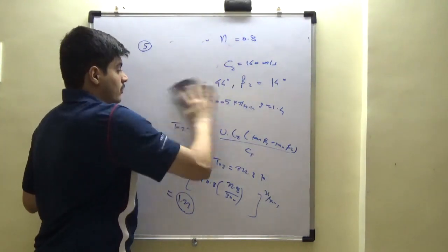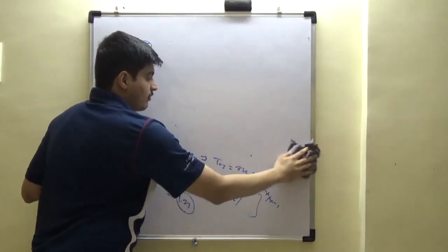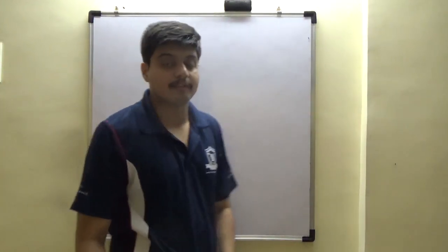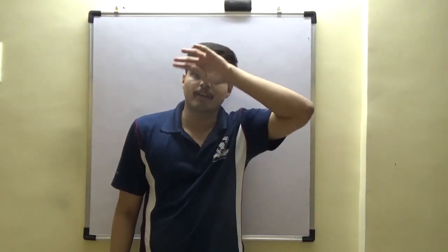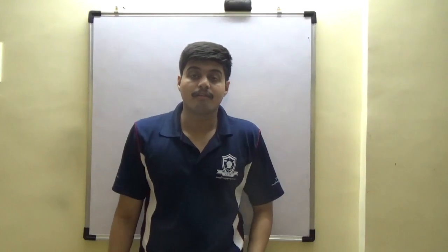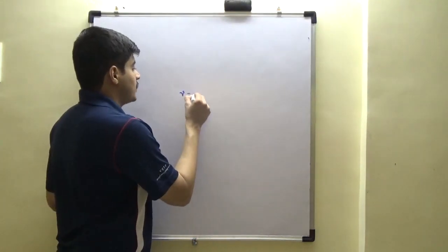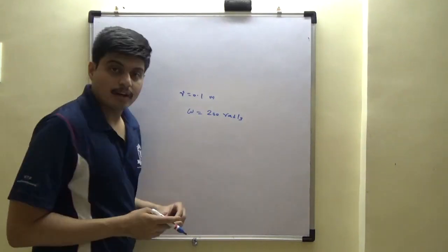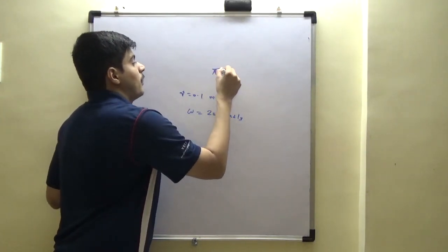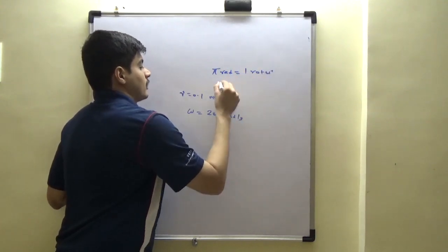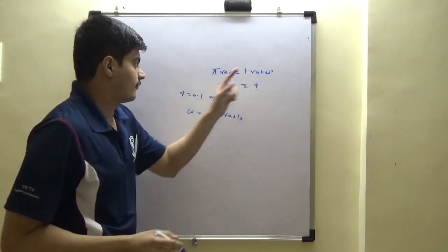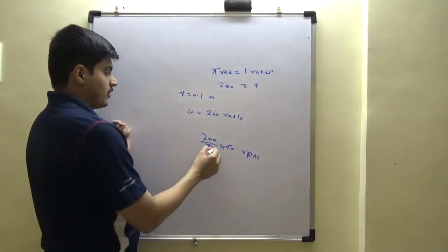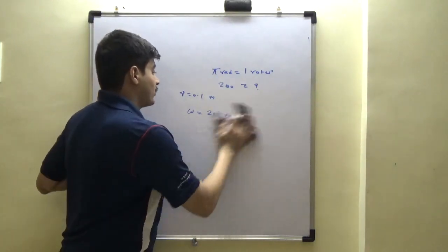You may feel this is very, very low and your observation is very correct. Now we have to guess ourselves why. This is not asked in any question, but this is your own introspection to get more flavor. We said blade speed is 200 meter per second, which is quite high. It's a decent enough velocity. If typical radius is say 0.1 meter, omega is 200 rad per second. How do you convert rad per second into RPM? Pi radians is 1 rotation, so 200 radians is x rotations. So 200 upon pi into 60 RPM. This you can simplify. So it's about 4000 RPM.